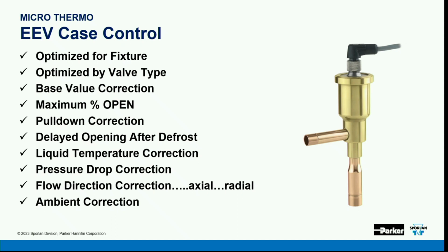Delayed opening after defrost, liquid temperature correction, pressure drop correction, flow direction. Do you know that our engineers found out if you feed the liquid on the inlet to the radius versus the axis, okay, so we talked, that's radial input, that's axial input, the valve actually performs differently.